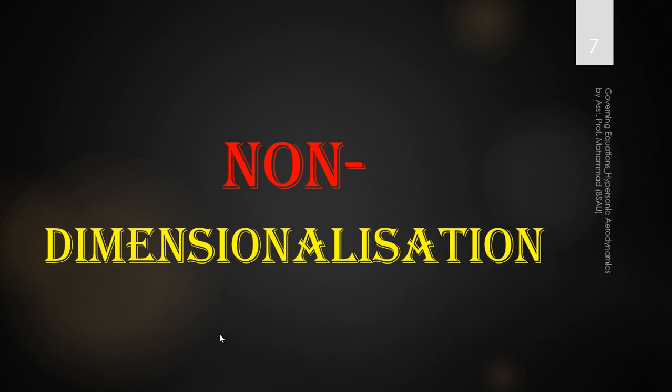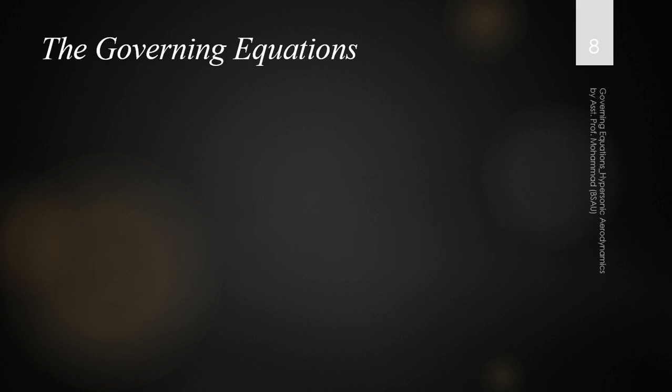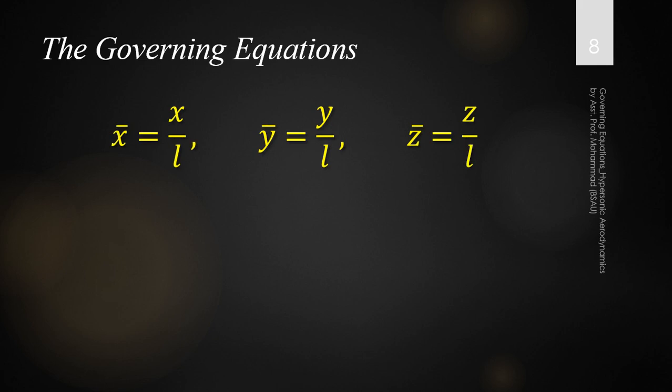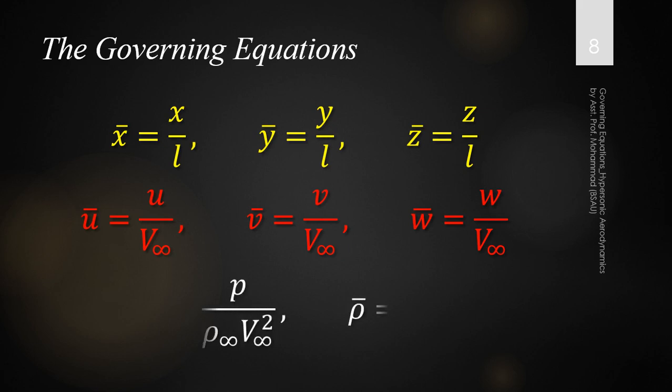Now let us try to non-dimensionalize the equations we have just gathered, which are actually governing the flow field. We come to the governing equation again. For non-dimensionalizing, we need some reference parameters, so that we can non-dimensionalize our variables and all these relations.